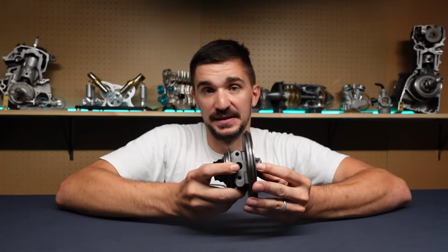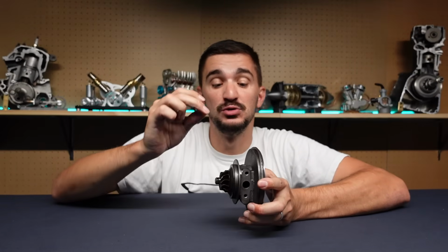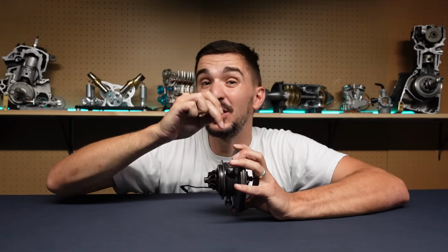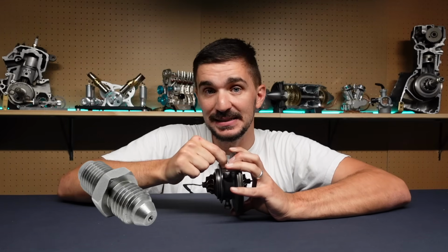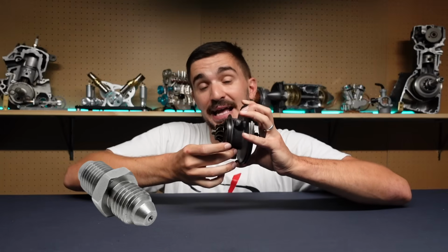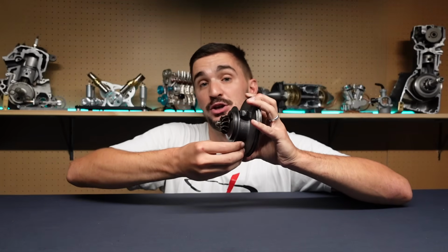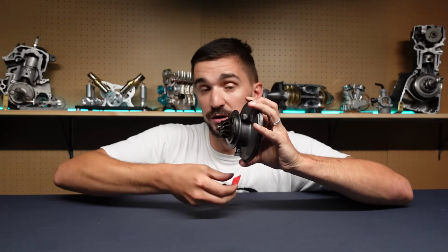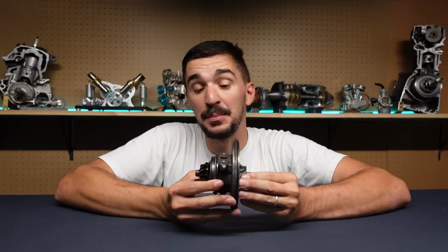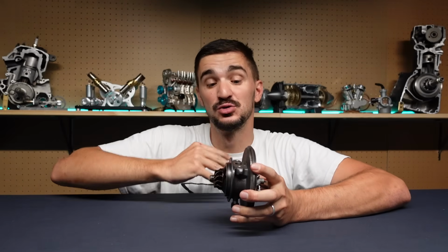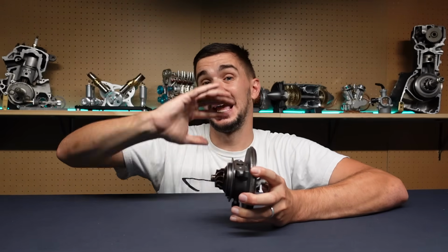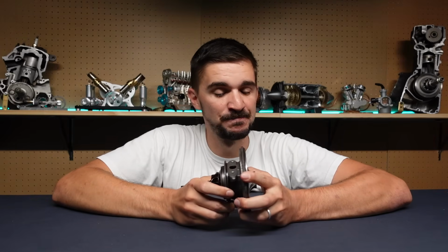The added benefit of ball bearings is that they require less oil, so they tend to have oil restrictors in the oil inlet, which means that there's also less oil coming out from the turbocharger and going back to the engine through the oil return, which means that setting up oil return can be easier with a ball bearing turbo because there's less risk of the oil coming back up and you getting a smoky turbo.